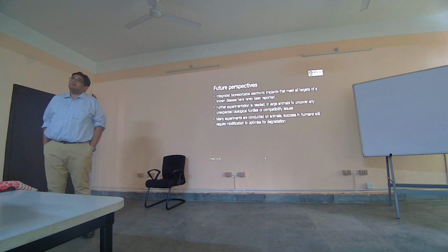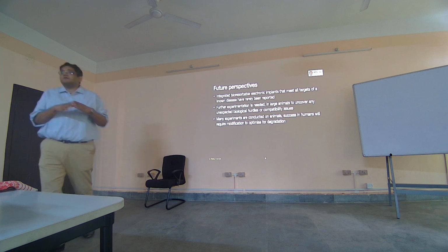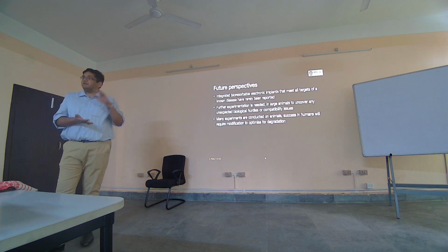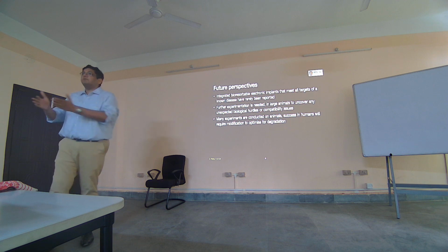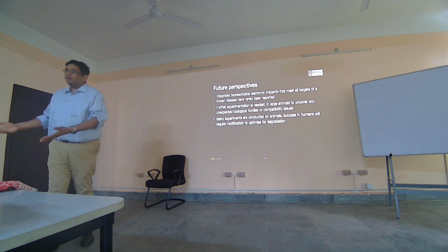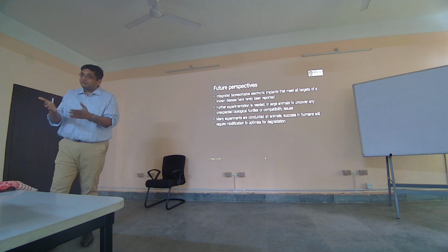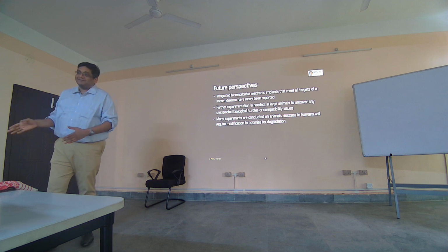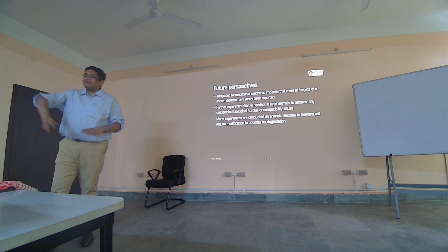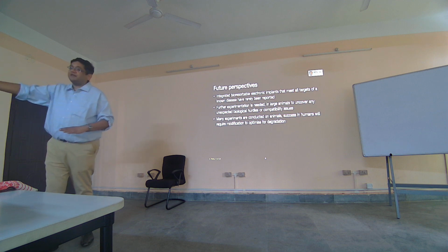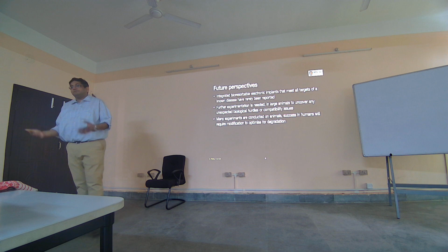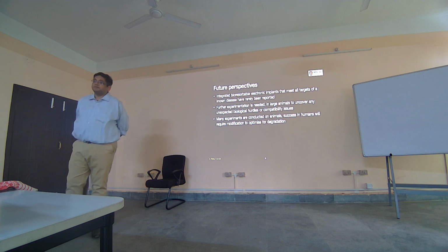Today, if you look at the way people are publishing, in the university it's very hard to create this entire processor from start to finish. So what people do is create the crossbars and then do the post-processing in software and then report results. Even the nonlinear function, they implement in software. They do the crossbar and then send the output to an FPGA where they do all the rest. So that's how it's published, but in reality, we have to do it using some sort of a device.